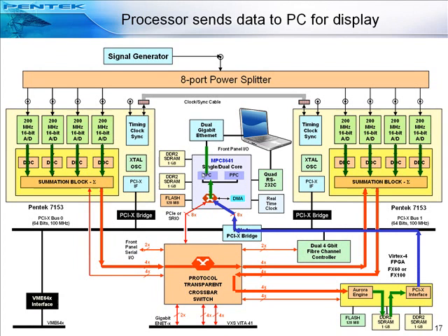The PowerPC creates a beam-formed pattern display and presents it via its front panel gigabit Ethernet port to an attached PC for display. So here is our complete beamforming system with all signal paths shown. Notice how the crossbar switch makes it simple to set up exactly the right data interconnection paths we need.